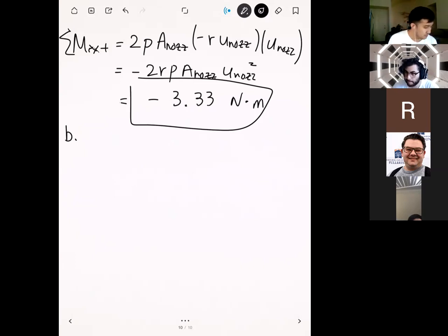Okay. So I know, the tricky thing in these control volume problems is always going to be the signs, because there are so many different sign conventions here. So we have our Cartesian sign convention, we have our inlet and outlet sign convention for the carrying velocity, and now we have the right-hand rule for angular momentum problems. So it's hard. I know it's a lot to keep track of, but as long as you take each term individually, go slow, one term at a time, I think that's what makes these problems a little bit easier. So don't assume that one term will have the same sign convention as the next term. You really have to question each and every term in your RTT.